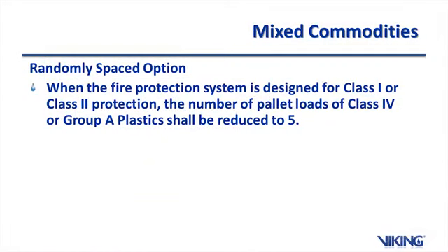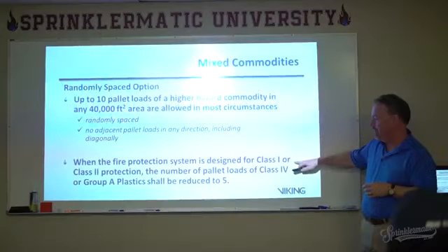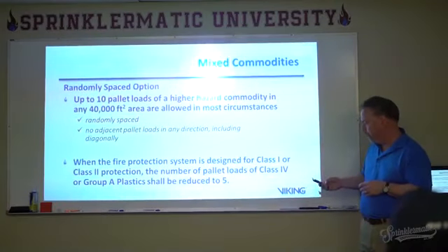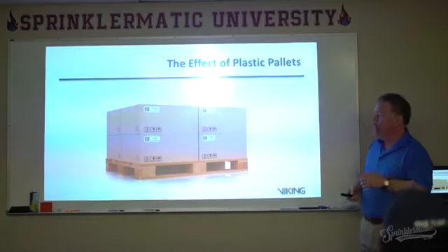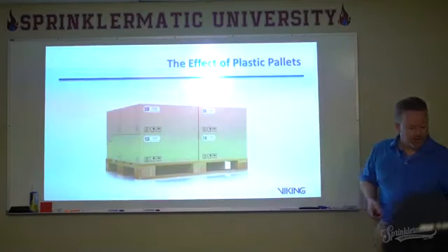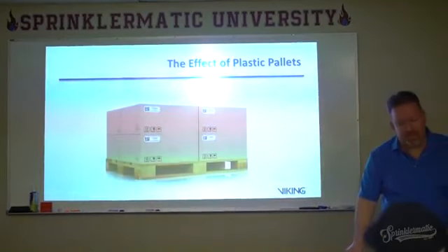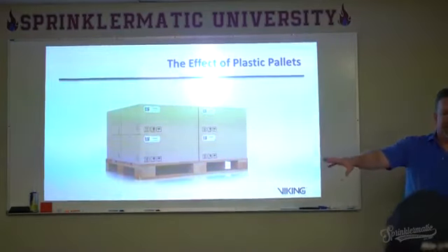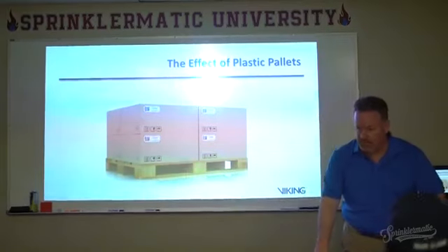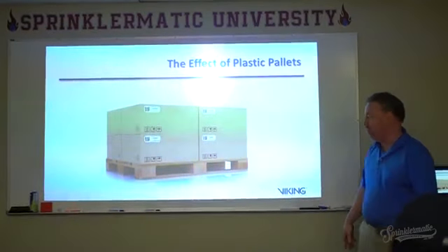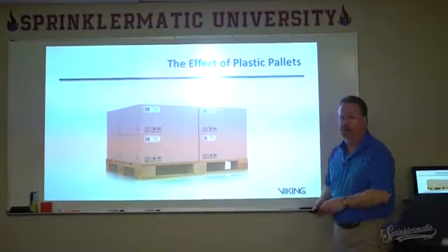That's where the number of pallets of Group A can be reduced to 5, when the fire protection system is designed for Class 1 or 2. So that's the impact of Group A plastics on others. That's the mixed commodity requirement, or the mixed commodity challenge. Now we've got to take a look at